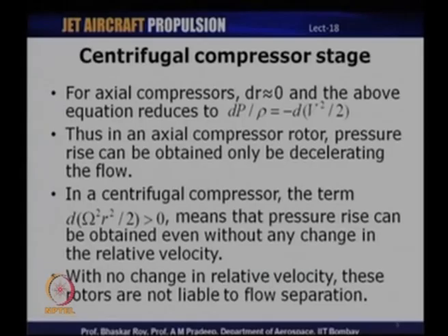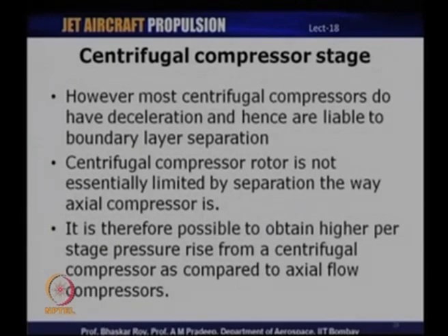So, with no change in relative velocities, it means that centrifugal compressors are not really subject to issues of flow separation. But most of the modern day centrifugal compressors also have a certain amount of deceleration taking place, which means that they are also liable to separation in some sense or the other. But the essence of this is that the centrifugal compressor rotor is not limited by flow separation to the extent that axial compressor rotors are. Axial compressor rotors suffer heavily because of flow separation issues, whereas centrifugal compressor rotors really do not have that problem.